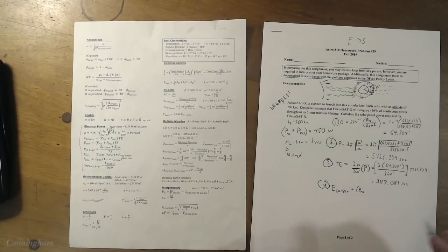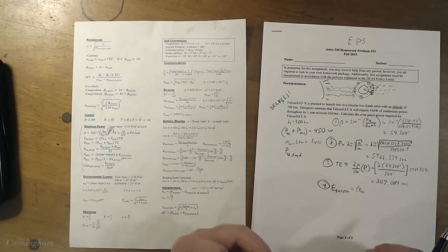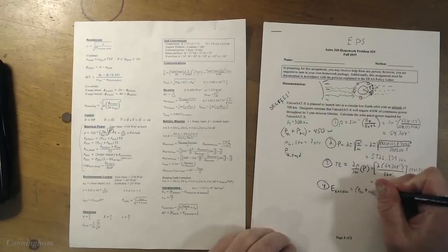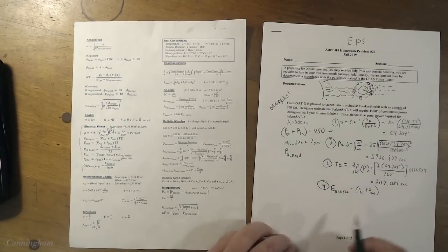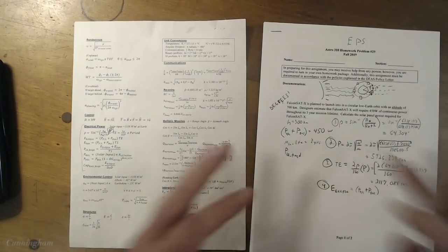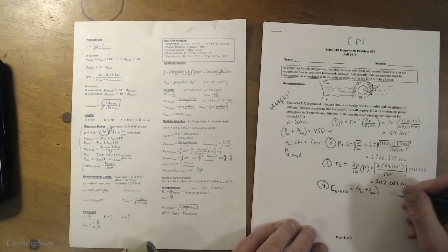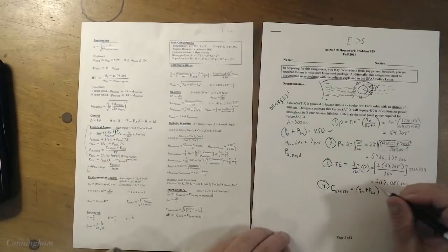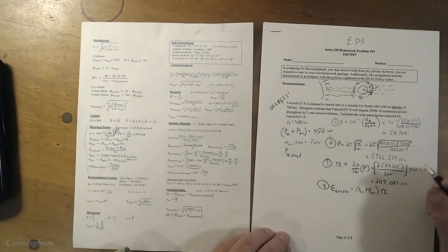That's the thermal control subsystem and the comm subsystem and the pointing subsystem and all the other subsystems that need juice, but they're part of the bus. The problem tells us that the total amount, it doesn't break it out into payload and bus, but it does say the amount that's used by both of them all the time is 450 watts. And the equation sheet tells us to multiply that by the time of eclipse we just found.